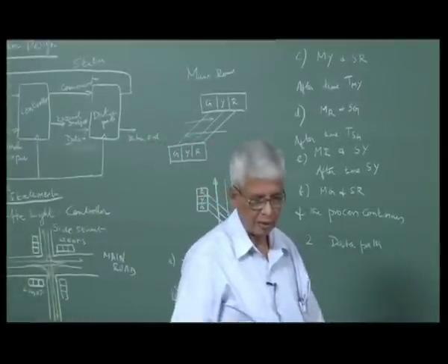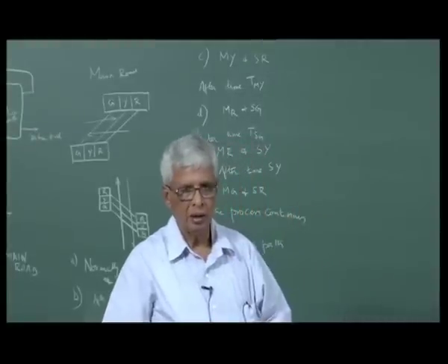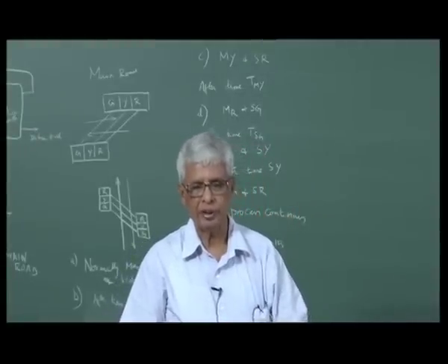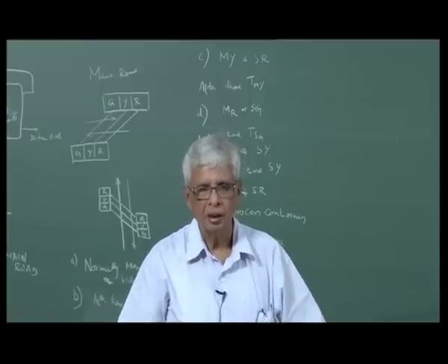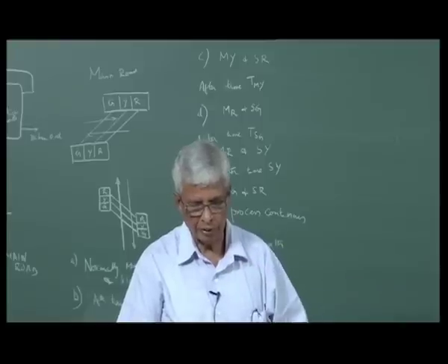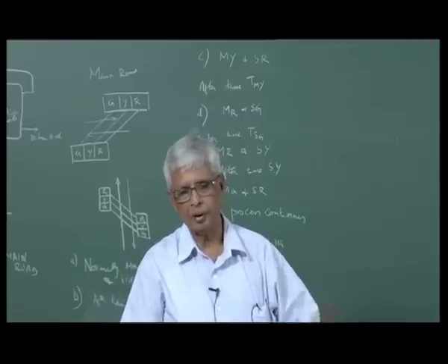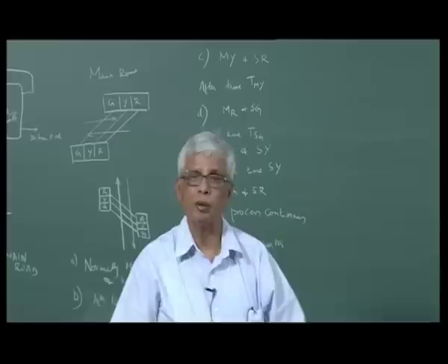For example, last time for the multiplier, we took an adder, registers, some of them shift registers. We took a counter, and the counter was counting from n to 0. When 0 was there is a comparator. That Z was the output that went to the controller. All those things are data path.